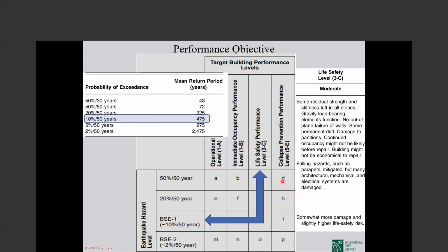For example, if your building is important, you can say, I want life safety under this level of earthquake. So explicitly, you can select what you want from this building, instead of implicitly trying to reach a performance level by a factor, for example 1.5 or 1.4, when there is no guarantee that if you increase the design base shear by 1.5 you get better performance.